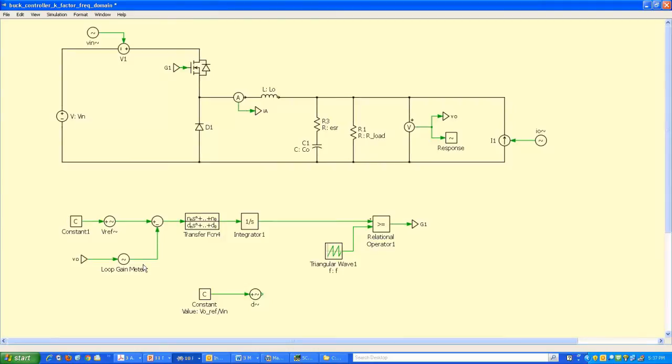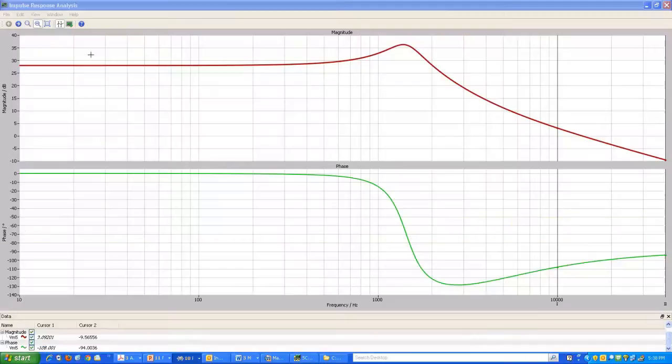Okay. So whenever I do the small signal analysis, I can only select which perturbation and which response I am interested in, and when I do that, the other perturbations do not affect anything. So I can still retain all the other perturbations. They don't really impact my loop gain measurement. So that is done here. Let me go ahead and do the small signal analysis.